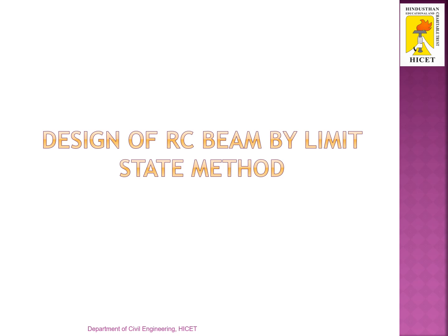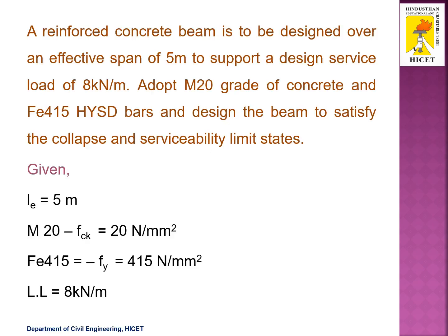In this video, we are going to design a RC beam by using limit state method based on one problem. A reinforced concrete beam is to be designed over an effective span of 5 meters to support a design service load of 8 kN per meter. Adopt M20 grade of concrete and Fe415 HYSD bars and design the beam to satisfy the collapse and serviceability limit